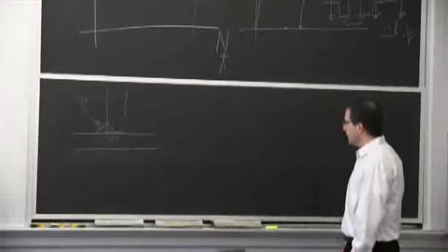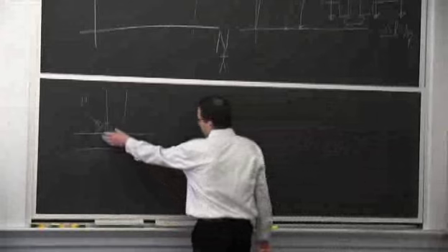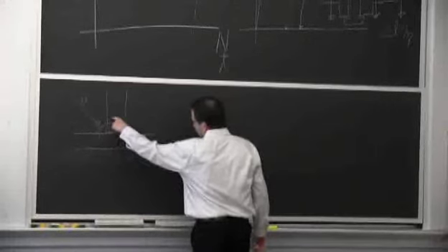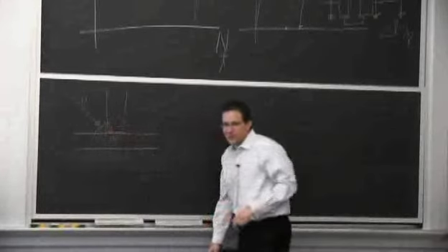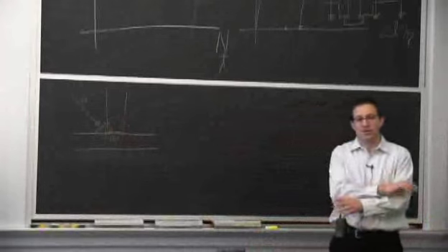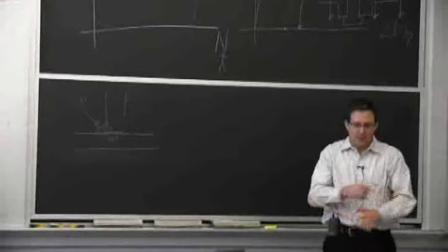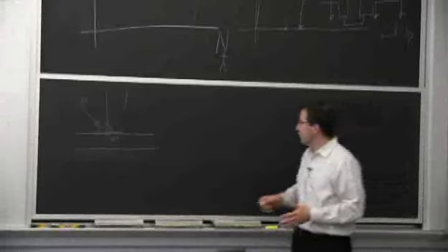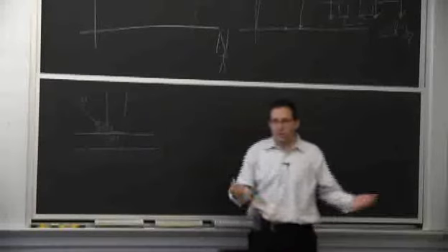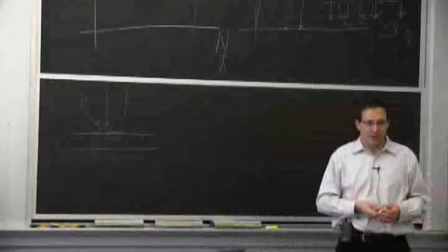And you can probably think of this, and that's going to become intuitive to you, just even the way it's set up here. So this is melted at some point in time. This is hot, and this is cold. So when everything cools back down, you'll have distortion. There's just no question about it. If you restrain the pieces, so you keep, say, 90 degrees between this one and this one, then you'll build up residual stresses. So it goes one way or the other.